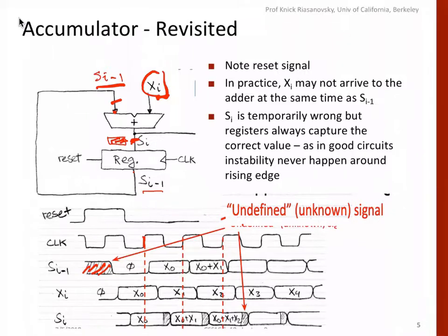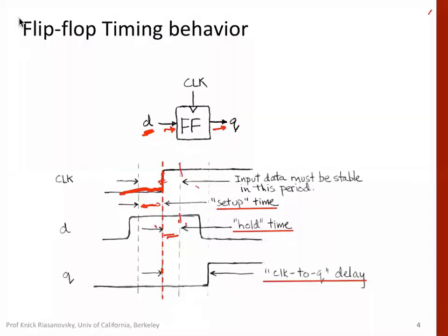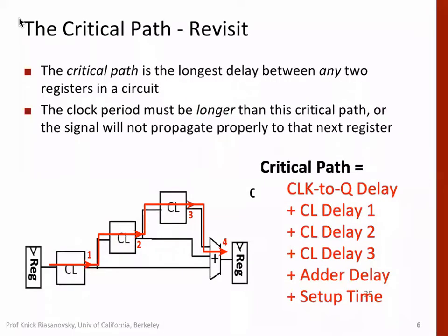It takes some time for the register to accept the input that's available. Although we say instantaneous, it takes time, so the input D, or the inputs coming to the register, should remain stable for some time after the leading edge of the clock. That's the reason we have these two periods, setup time and hold time. So with this knowledge, let's go ahead.